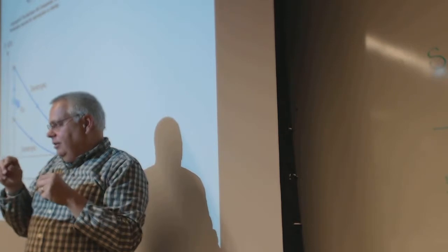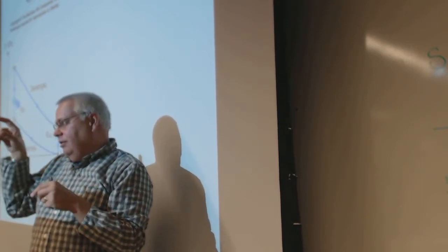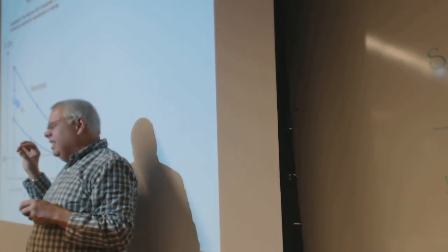Q, the quantity of heat, is C sub P delta T. Well, for a constant volume process, it's a C sub V constant, C sub V change in temperature. So we can predict this temperature. There's two things going on. Either they can tell us what the maximum temperature was, and we predict what this one was, and then we can back into how much energy would result in that temperature, which is basically solving for Q, or they can tell us how much heat went in.